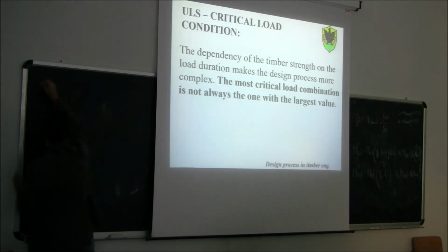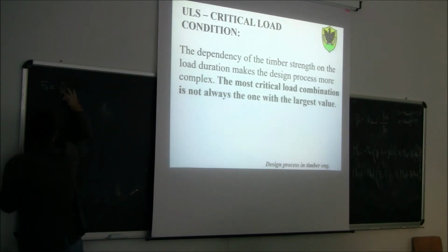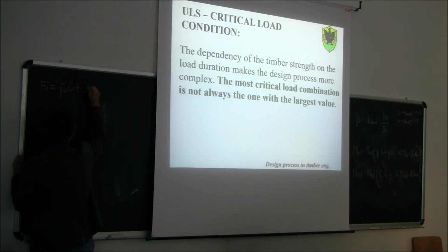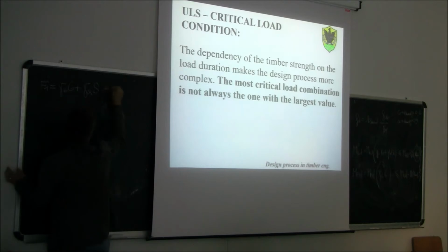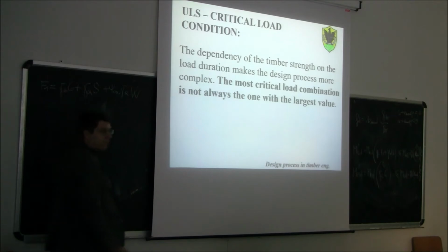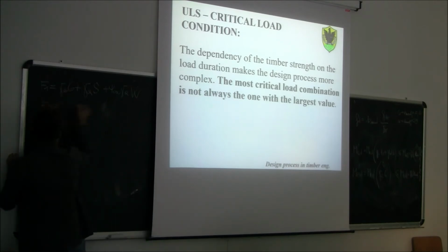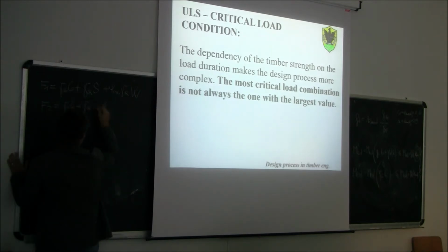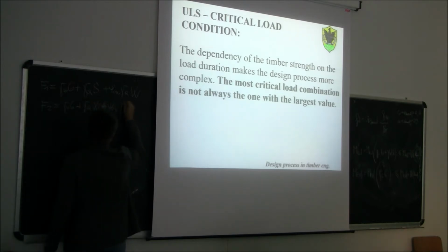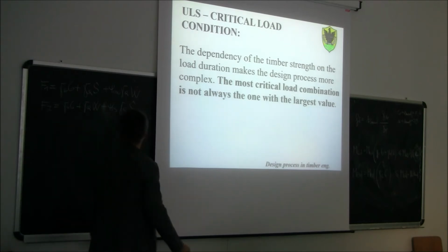So, the first one, with snow as the basic action and the wind as the variable action. Okay. The second one, the opposite. The third, only the permanent load.